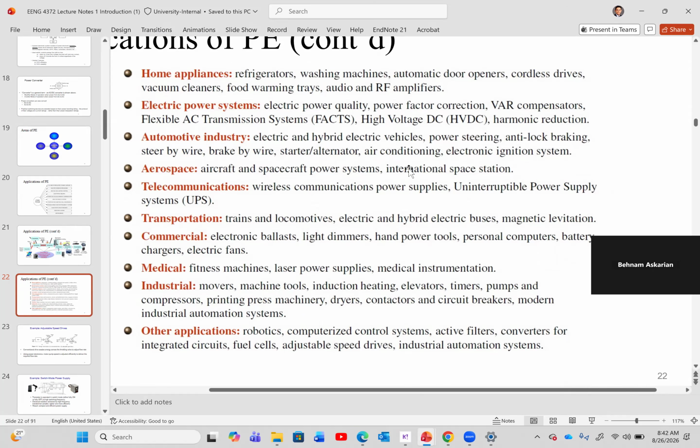Even EVs, some of you may not know this, but all electric vehicles also have a 12-volt battery. That 12-volt battery is essential to keep simple electronics running, like the door locks with a remote control, or even opening the latch for the EV charger. If the 12-volt dies, the whole car stops working.